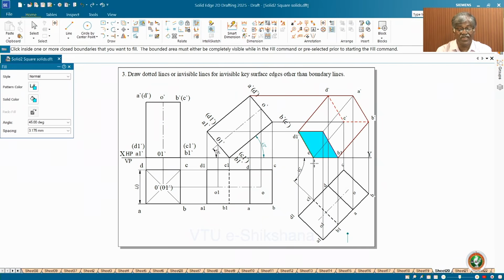But some people may say, why do you complete up to this? You stop here. No, it is an edge which is completely available but not visible. So entire CC1 is dotted because visible surface, invisible line. Okay. Now I can complete this line as dark, this line as dotted. This is dark because of visible bends, and this is dotted because of invisible bends. Or I can say crossing line. This is dotted because of crossing line.